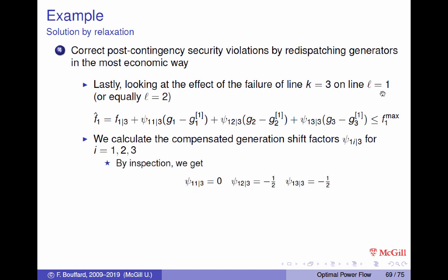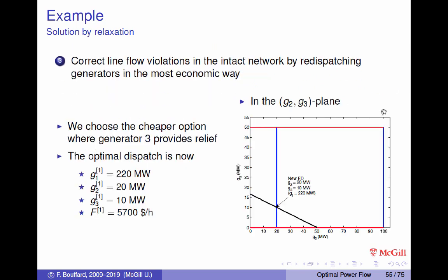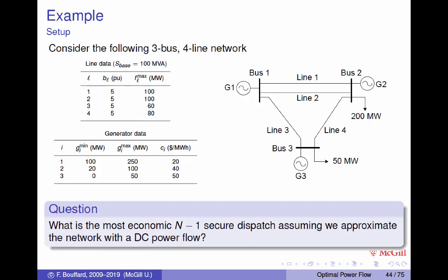So here, again, going back to our power system. If we lose, in this case, we lost line 3. So if we have anything coming into node 2 being taken out at node 1, line 1 and line 2 are identical, so the power is going to split half-half, 50-50, and we're going to have a negative power flow. And here again for node 3, we inject 1 megawatt. It's going to split 50-50 again towards the slack node over here.